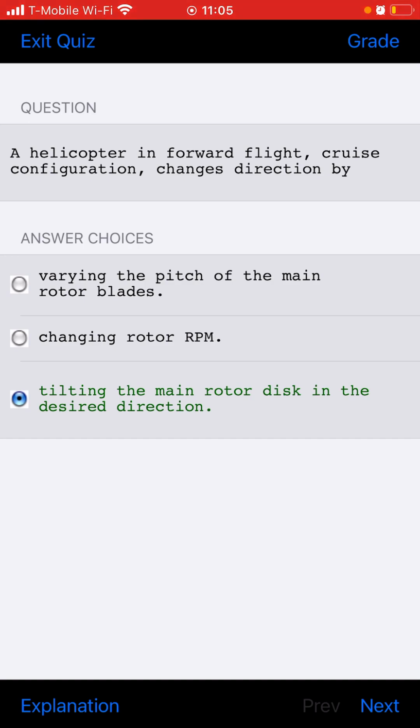The vast majority of aircraft control cables are terminated with swage terminals. They must be checked with a go, no-go gauge before and after the swaging operation to show compliance with the manufacturer's requirement.